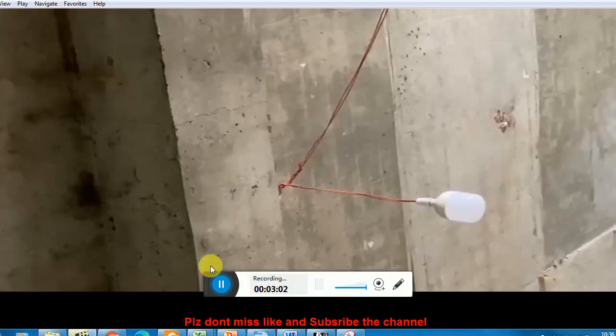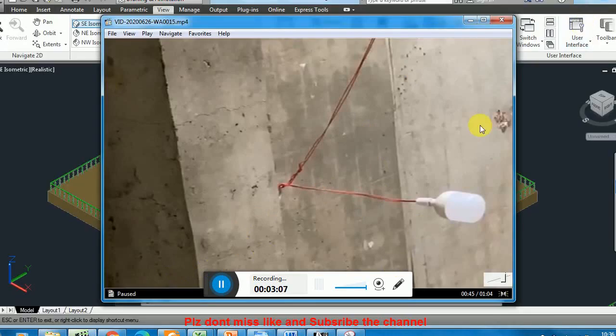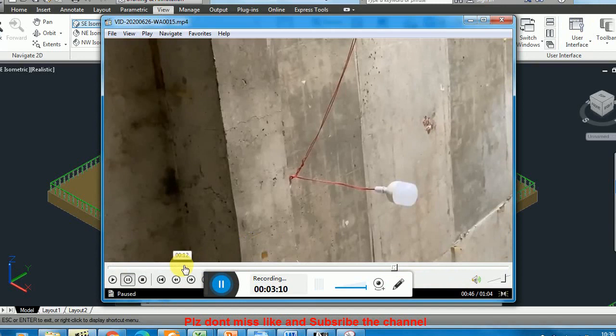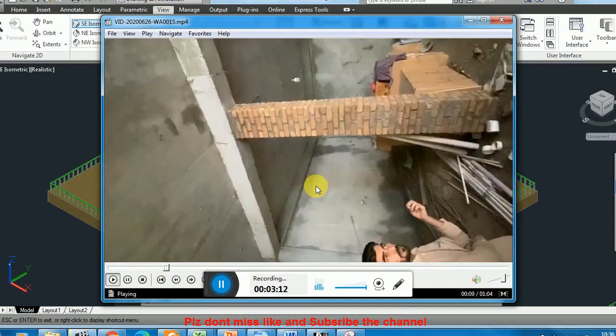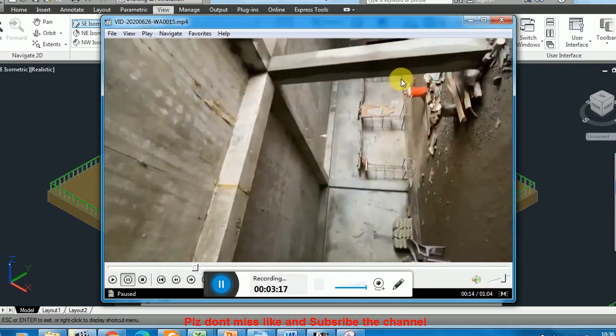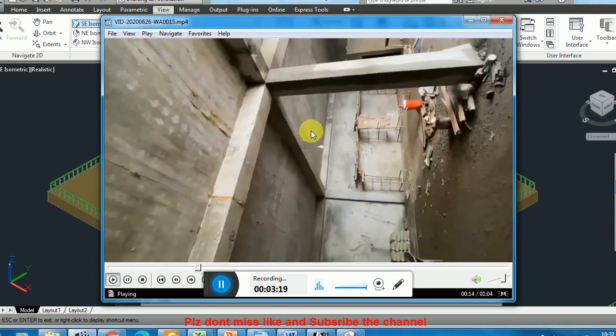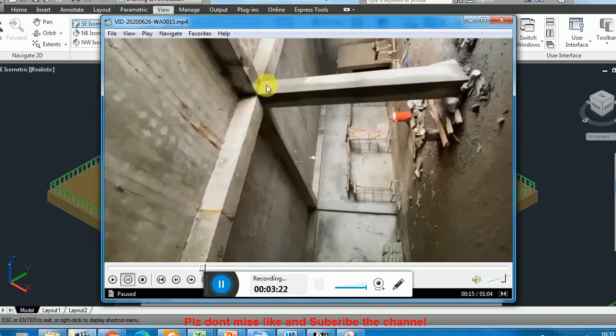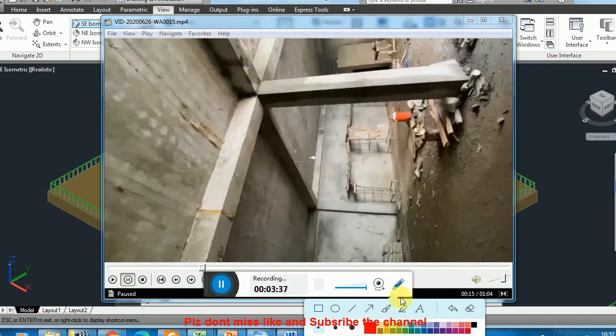Let me show you this video, and I will explain how important the design of a column is. Okay, here you see basically the column, like let me show you this column. You see, practically there are 4 beams coming over this column, and since this is an axial column, because all the spacings are the same, the most critical problem occurred in the design of this column, that this column buckled out.